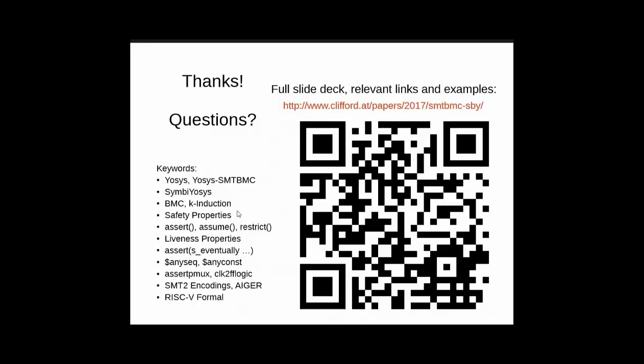But I think those tools are all BDD based. So it's really, really hard to get them to argue about very, very large systems. So some of the systems where I can prove non-trivial properties have and-inverter graphs of over 2 million nodes. And I know that with a BDD-based approach, this is just not possible. It's just your opening slide said there weren't any that people could just download and use, and I believe students can.